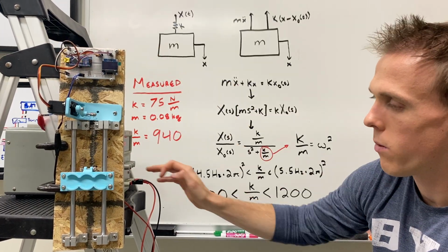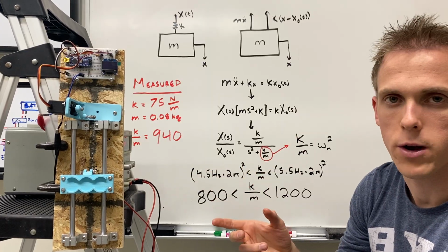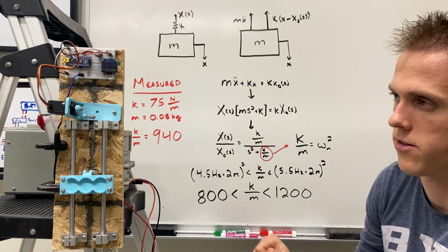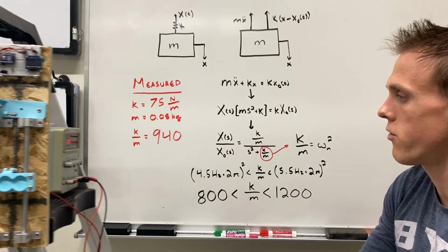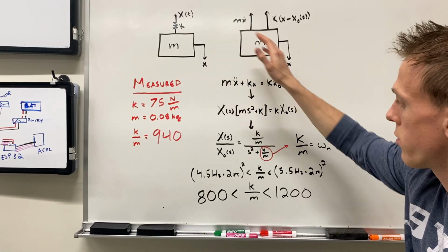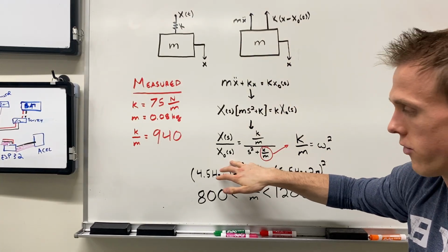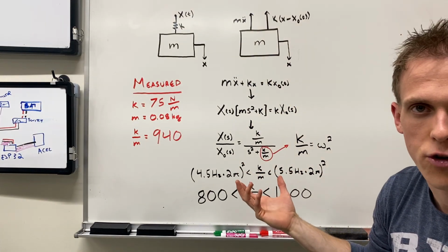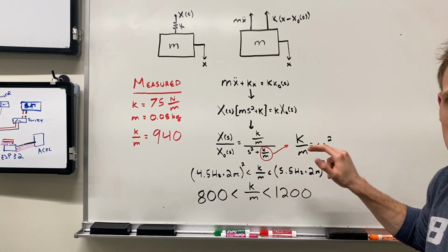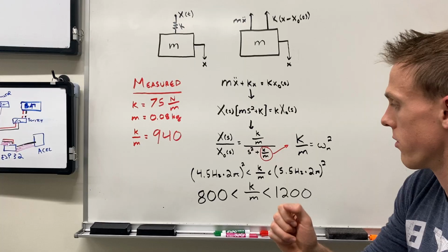And so my goal was to use that observed natural frequency to guess the mass or spring constant of the system, the physical parameters. So I'm going to push this out of the way so you can see the math. It's a simple mass spring system, and going through the math, it yields this transfer function. And so the most important term of the transfer function is the k over m, because that is equal to the natural frequency squared, and that's what we observed in our physical system.